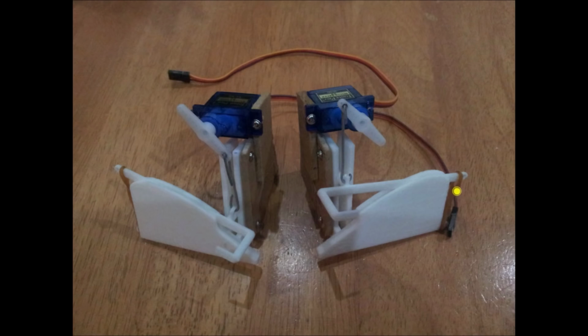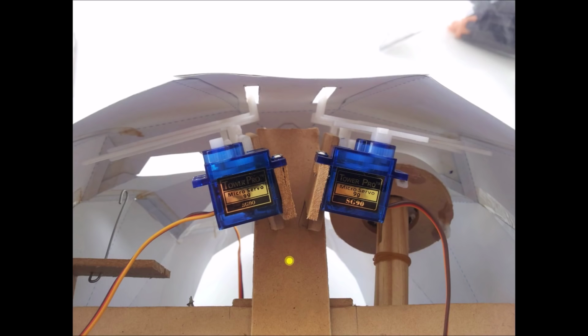Here you can see the final eyebrow mechanisms. Here's the guide mechanism that was 3D printed based on the Fitzpatrick work, and the guiding arm where the eyebrow attaches here once it's gone through the mask feature. Servos at the top simply move up and down to control the up and down motion of the eyebrows. Here's a photo test fitting the servos to see if they've got enough clearance around the eyeballs and to make sure that they lined up nicely with the slots in the face.